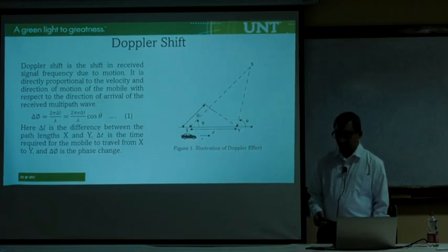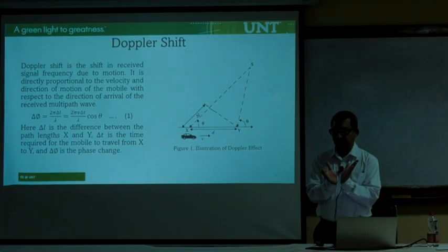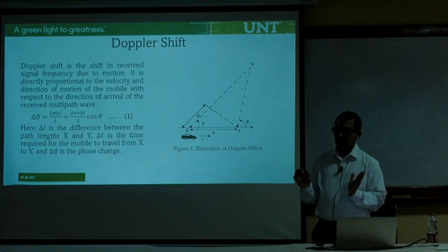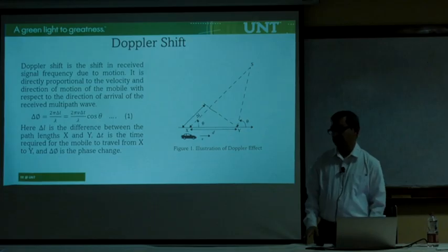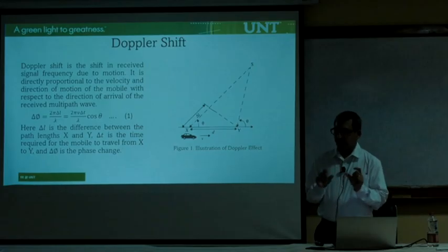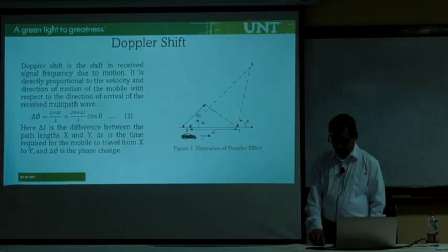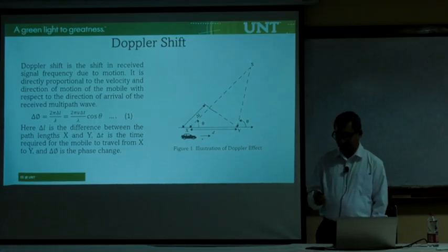OTFS: if you design the resource blocks, the resolution of the time-frequency blocks, appropriately, then the impact of Doppler shift won't be there. It's the same for the other modulation as well; you need to design those resolution levels expecting what kind of Doppler shift you can handle. In fact, we'll probably talk about that in the last class on the last day.